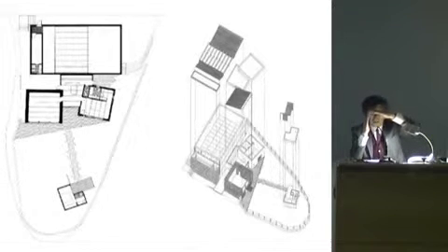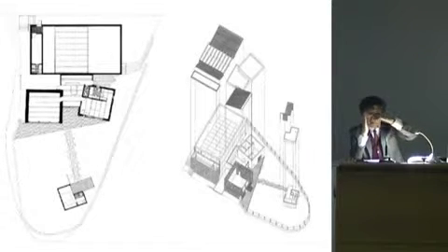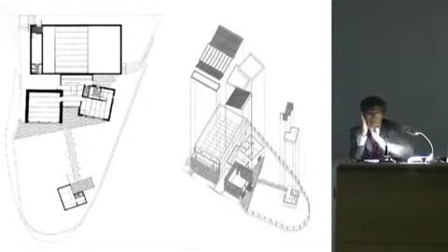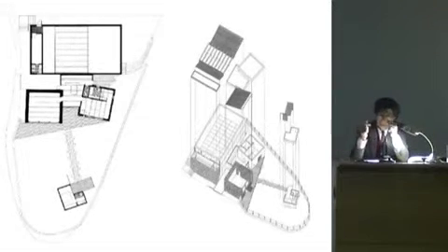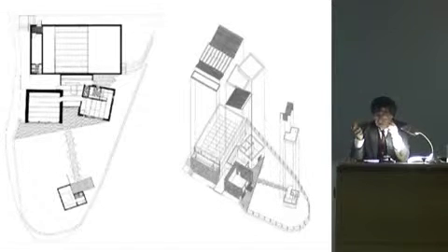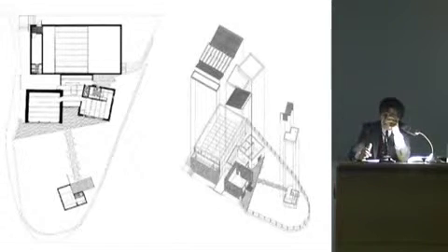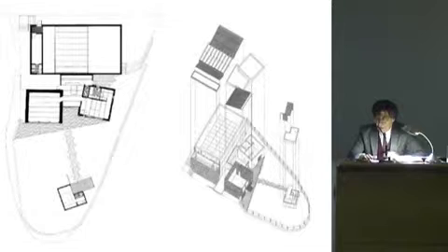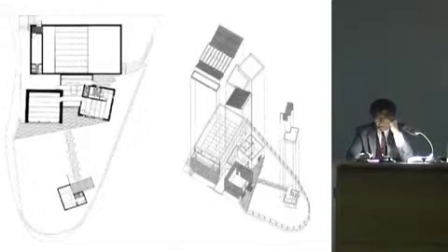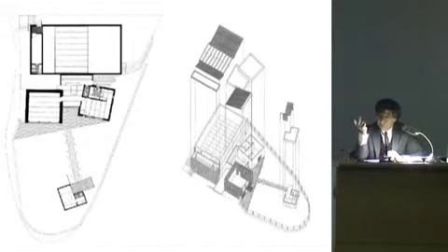with structure, because if you have the exterior load-bearing wall, the beam rises, and when rising it breaks, and then it fissures, and then it loads down onto the interior partition wall, which is not ready to bear that weight. Isolation is behind the wall, then the wall is much more permeable, and it's the wall which is the load-bearing wall, and it's just not good from the climatic point of view, and there are other problems related to it, the fittings, the grooves, because you need to have access to the wall.